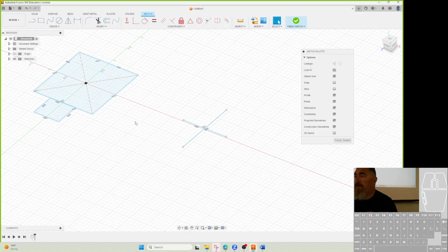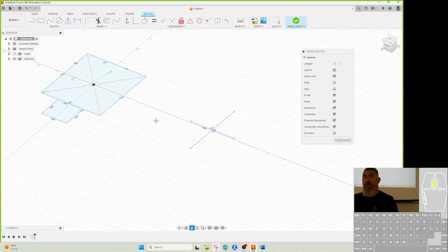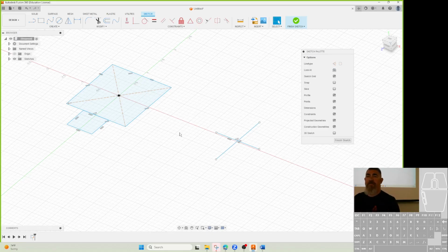All right. So now we're going to go into talking about how we can measure some stuff, and we'll do extrude, and then we'll get into measuring. We've been using mostly inches in this class so far today, but I showed you that you can mix the units. What if you wanted to just do everything in millimeters? Go to settings and change your base units.